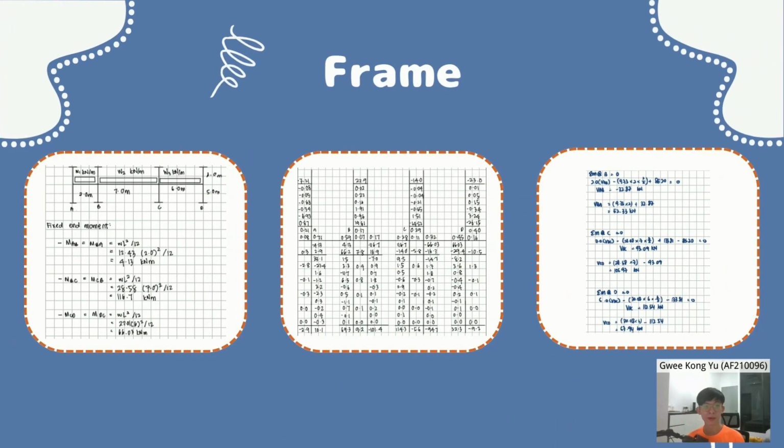Basically, these are the methods of the analysis, except for the wind load and vertical load method. But different methods will have different reference calculation points. So first, we have to find the actions to obtain the fixed end moment. And then we do the moment distribution, and finally we can calculate the shear. And these steps will generally be repeated with different cases.